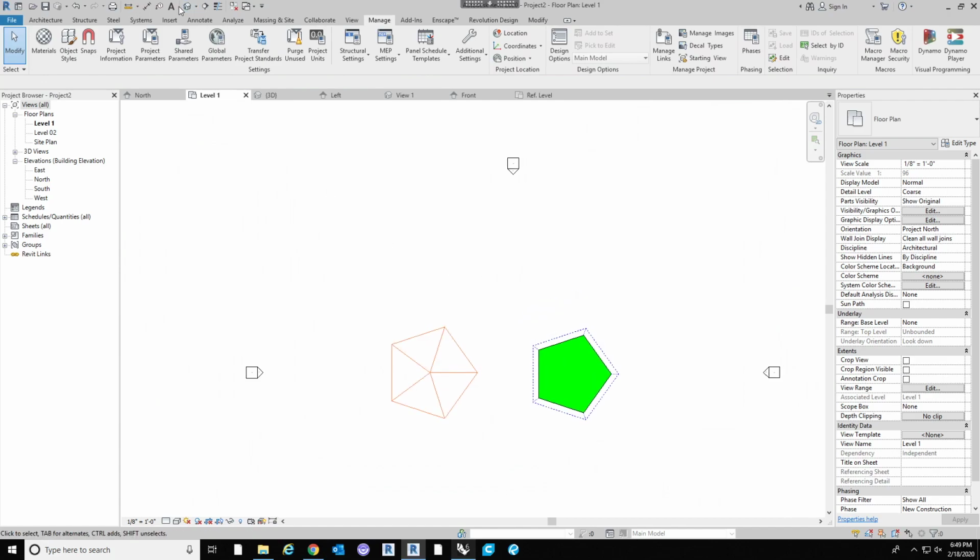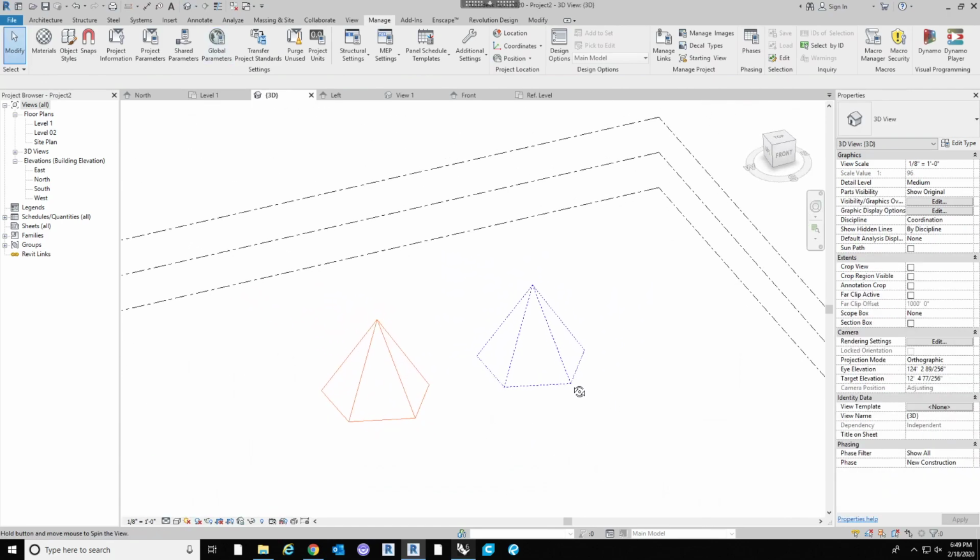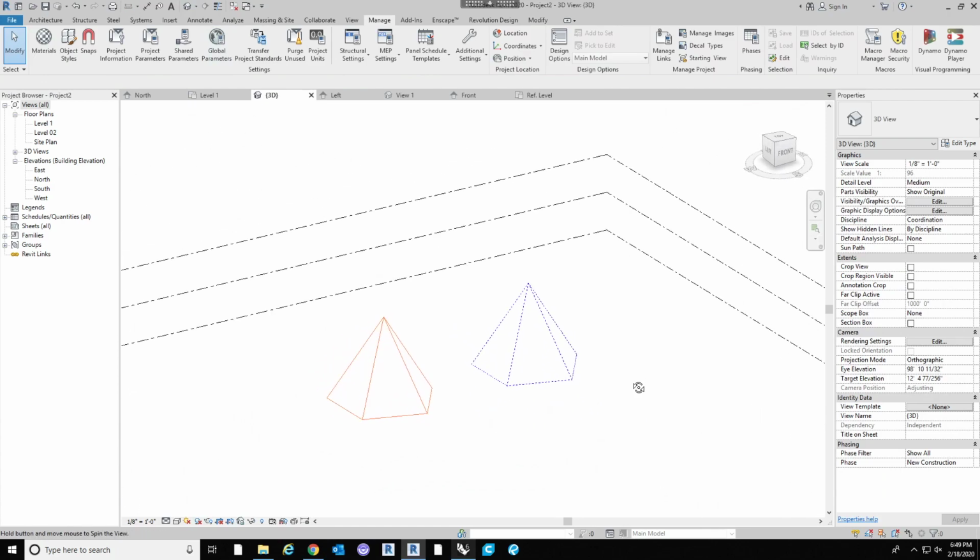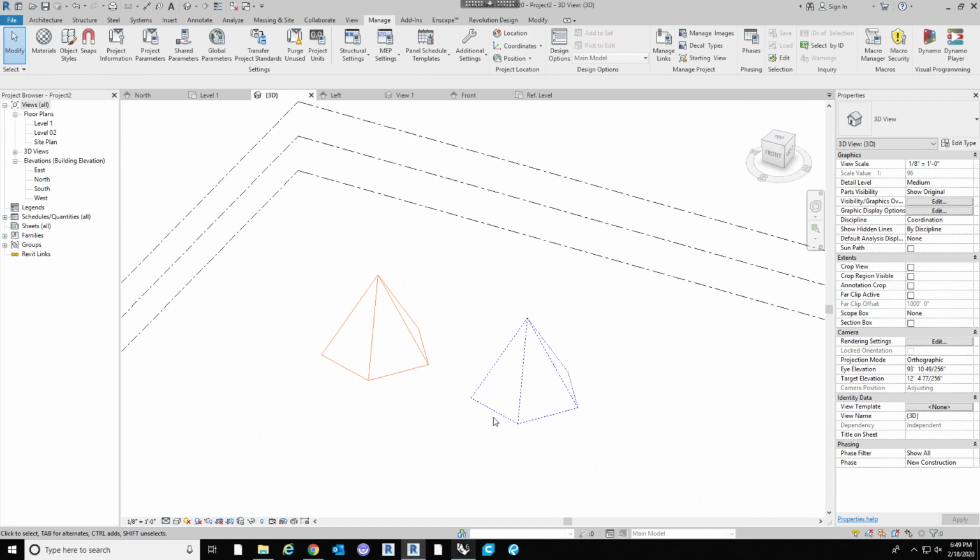All right. So those are two different ways to import CAD or your Rhino files directly into Revit. But the one thing with these imports is you cannot manipulate them. What is done in Rhino is done, and you cannot manipulate it any further. That's why linking the file is really beneficial, because you can continuously update the Rhino model and relink it as you go to update the geometry that's in Revit. However, there is a way to import Rhino geometry into Revit and be able to manipulate it, and that's through the conceptual massing environment.